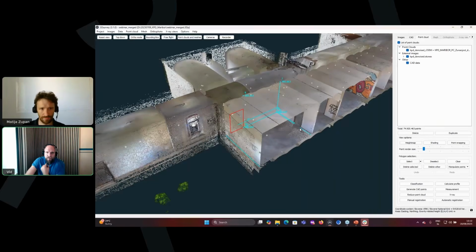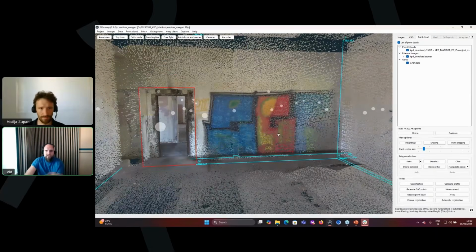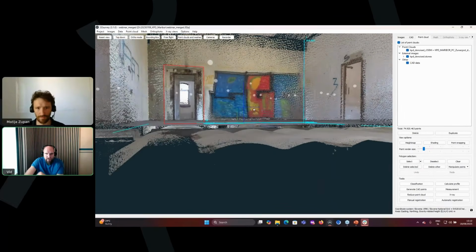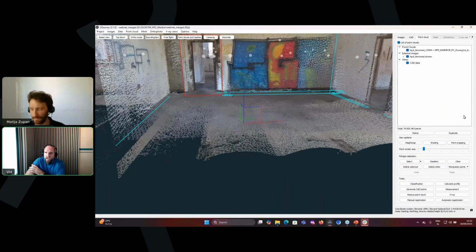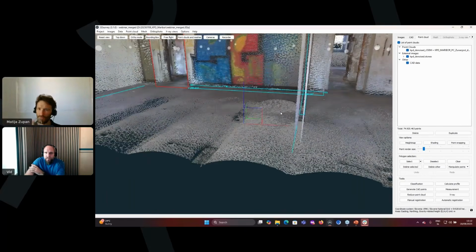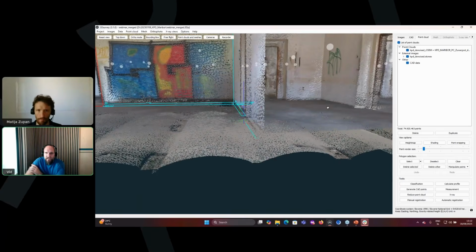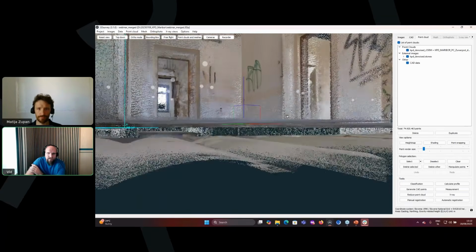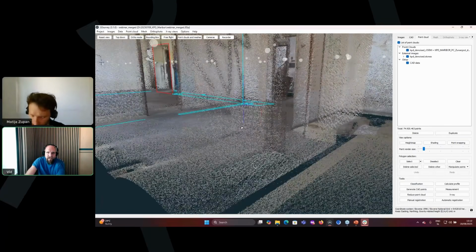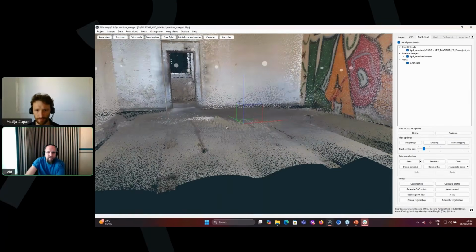Maybe if I just go back and quickly reshare my screen to check how much noise the point cloud has. That was done in the native StoneX app. So here we see, if we go in and zoom in, let's take the wall from the floor, for example. Here the points are a bit thicker. You see that the denoise algorithm works very well with flat surfaces. So this is perfect for the insides of buildings like that. The point clouds come out quite sharp.